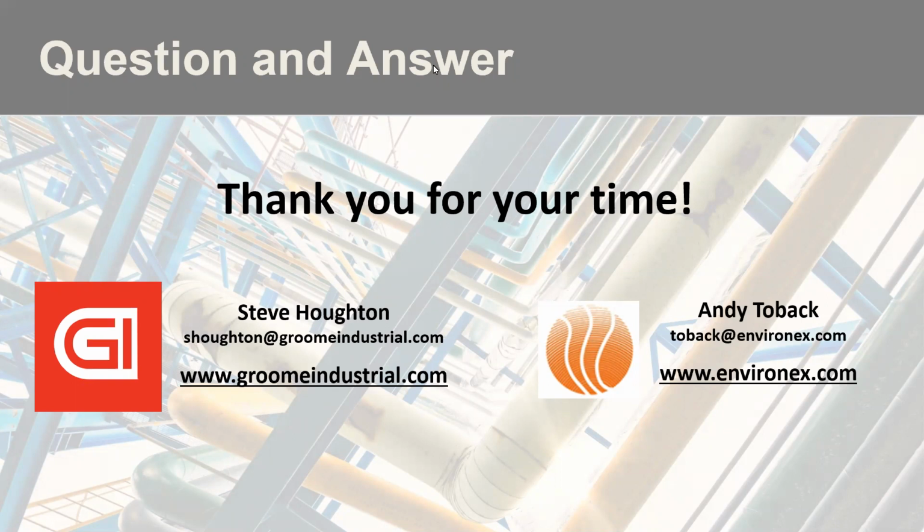You break the probe, then it's required to back up and make sure that your audit gases that the stack tester would bring are still measuring what they need to measure, so that when they put this new probe in, you're not getting new values that may conflict with the previous data you got with the old probe. So there's a little bit of, I would call it just growing pains of a day of tuning that exists. But in two 12-hour days, you could usually get a great tune as a result.